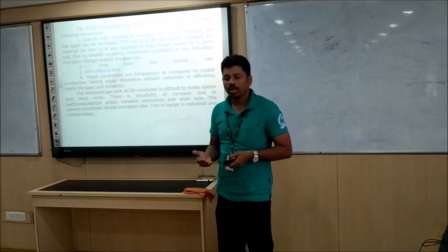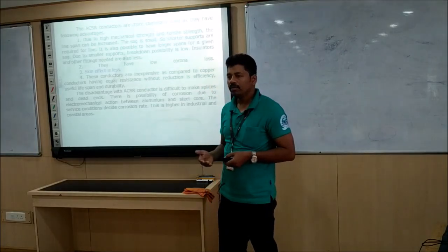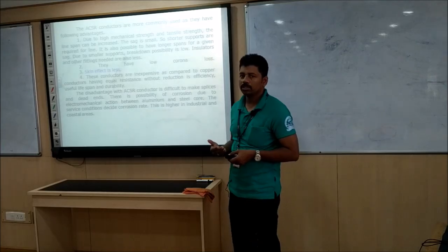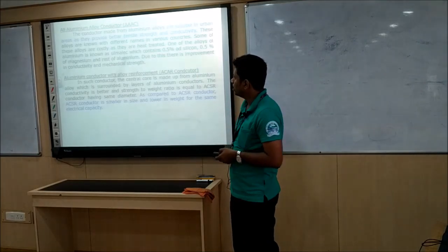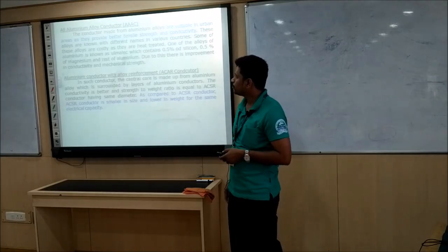To overcome that, we have to go for a standard conductor. Even that standard conductor is nowadays replaced with hollow pipes also. That is to reduce the skin effect.